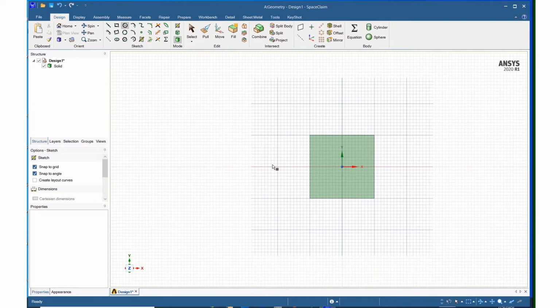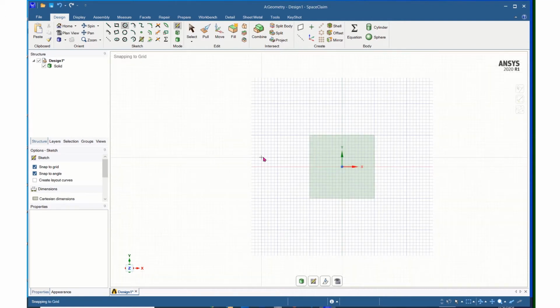I see that I have crosshatches on my cursor and I don't have the square to draw a circle, so I actually need to select this sketch plane. And now I have the crosshatch on my circle tool that I can use to select and build my circle. I'll come down 3 units from the top and click and drag out a 4 millimeter circle.